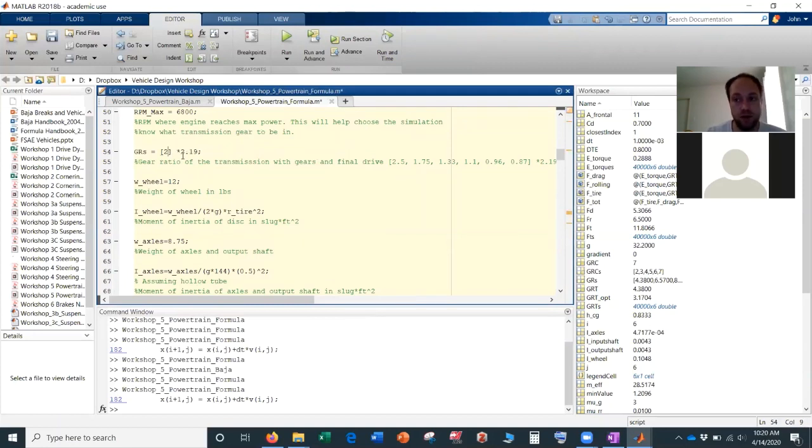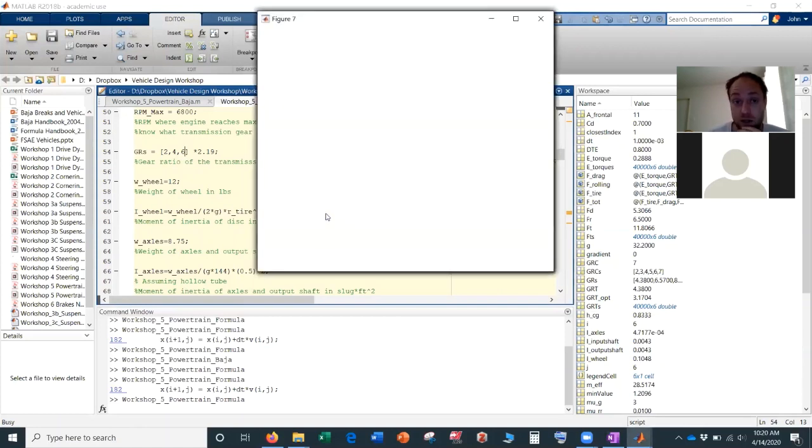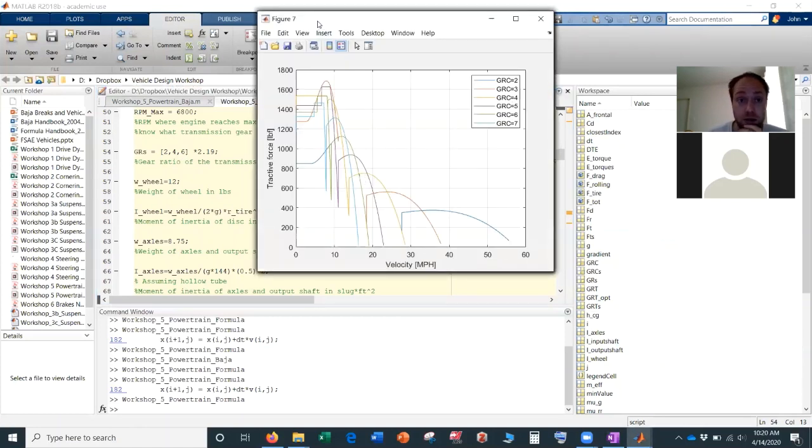So it should be 2, 4, 6. Right, so you can't really say, oh, we need a gearbox with ratios of 1, 2, and 3, which is 2, 4, 6, without talking about the sprocket, right? Because you can basically make those equivalent with different sprockets.